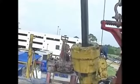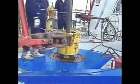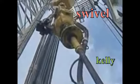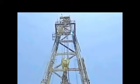The Kelly is fitted into a square or hexagonal opening in the Kelly bushing, which fits into the rotary table. As the rotary table moves, the Kelly and the Kelly bushing also rotate, thus turning the drill stem and bit below. As I said before, the top of the Kelly is attached to a device called the swivel. Allowing the Kelly to rotate, the swivel provides a passage for the drilling fluid to flow from the surface to the bit below, and also prevents the traveling block and hook from rotating while the drill stem is being turned.